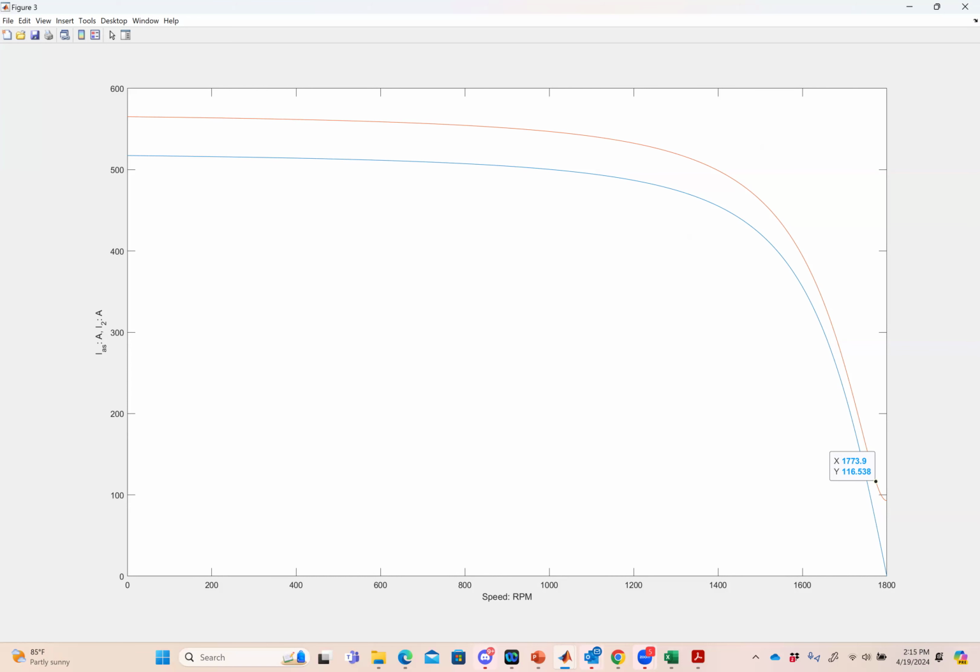Nowadays, you used to buy a motor and do what's called an offline start, right? When you do an offline start, you basically hook it up and it starts at 0 speed, goes out to here and operates at one speed. Nowadays, we use what are called variable frequency drives or VFDs, basically some power electronic box that controls the synchronous speed applied to that machine to make it go faster or slower, all right? We're going to look at that a little bit next week. But this covers the majority of what we need to understand about how an induction machine works. So I will stop there.